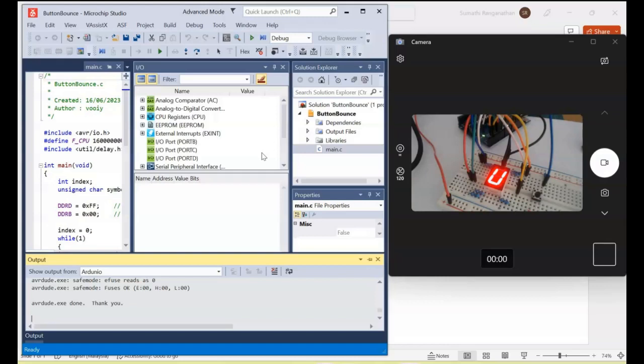Remember from my previous video, because I've been using all the RX and TX pins on the Arduino Uno board, that seems to be interfering with the uploading of the code. So my short-term solution is to remove the RX line. Now that it's uploaded successfully, I need to reconnect the RX line to the Arduino Uno, and we should have a perfect 0. Yep, so we have that.